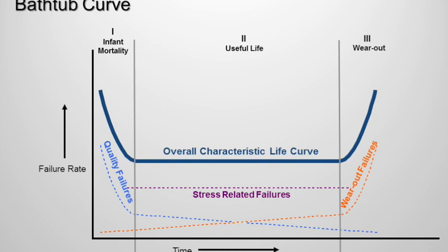At some point later on, the failures will begin to increase, and this will be driven by wear-out failures. So this is when predictable components will predictably begin to wear out, and you'll see an ever-increasing failure rate that will usually ultimately yield with the entire population failing due to dominant wear-out failure modes.